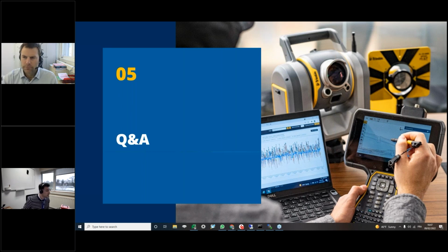I think the other question we already had was about the alarm. Can we set up an alarm in the Syscom sensor or in T4D web? In this case, you can do both. If you want, you can also raise the alarm on the Syscom, but based on what I presented on the platform, it is maybe easier to do it on T4D. So you will have all the alarms on T4D, but it is also possible to do it through the Syscom device itself.